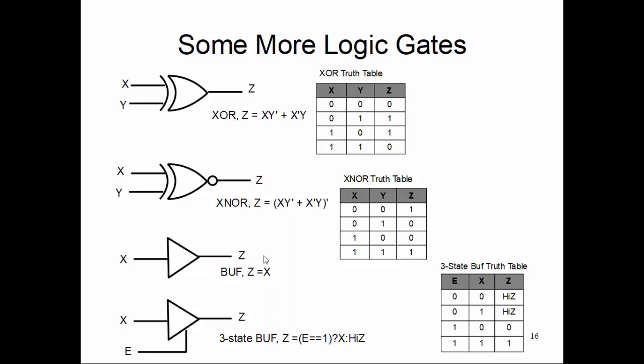Okay. There is one more component, we call it a tri-state buffer, which is a very special type of buffer, which is needed for electrical isolation from one circuit to another. Okay, so how it works: if E is logically 1, then you transfer the input, and this whole thing acts normally like a buffer. You put a 0, you get a 0, you put a 1, you get a 1, as long as your E stays at 1. Now if E becomes 0, then whatever logic is at the input side doesn't matter, your Z output becomes electrically isolated, like high Z. Okay, it is electrically detached from the rest of the circuit.